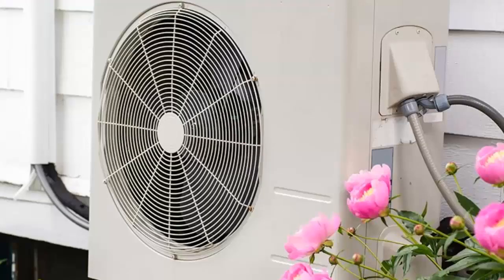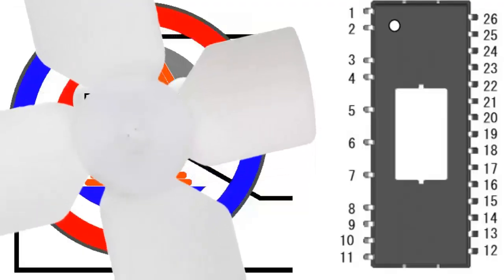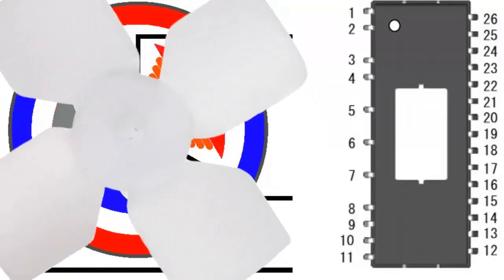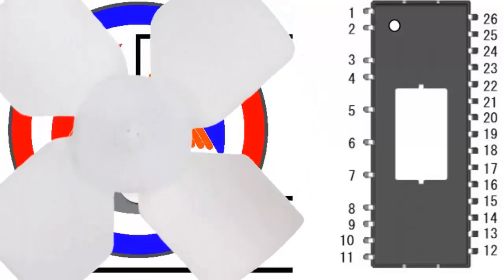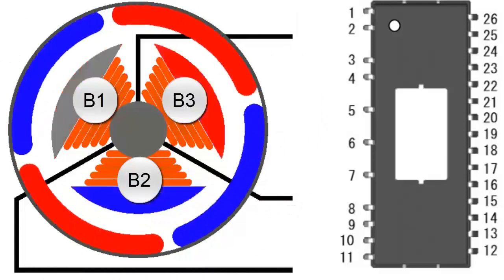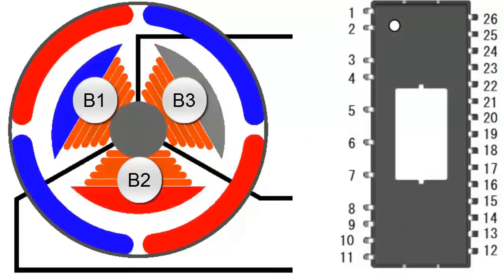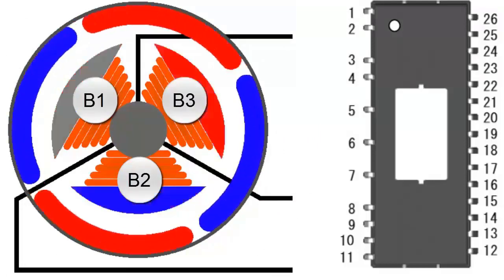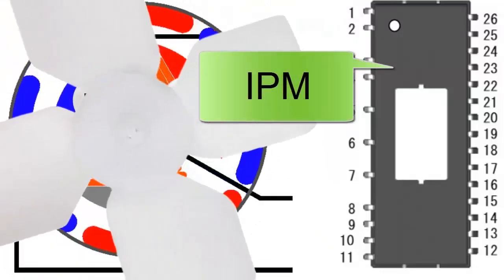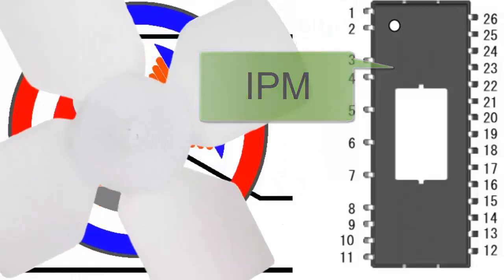In contrast, the BLDC motor used in the outdoor unit generally has 3 wires because its electronic board is inside the outdoor electronic board located in the outdoor unit. The 3 power wires are usually high voltage, ground, and speed signal from the exterior. The most common failure is located in the integrated circuit or IPM module that supplies power to the fan motor.